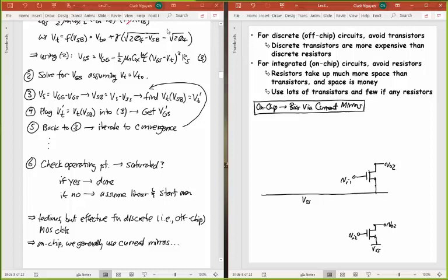On chip, you use one resistor. You still need to use a resistor because the way we generate currents, as you've seen with biasing bipolar or MOS, is basically to put a voltage across a resistor, and that creates the current. It's generally always the case. So anytime you want to figure out what the bias point of a circuit is, look for a resistor and find the voltage across that resistor. Then you can find the current, and that's going to pretty much determine the rest of the bias point.